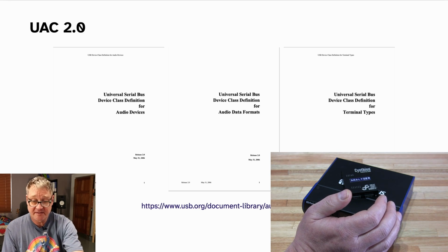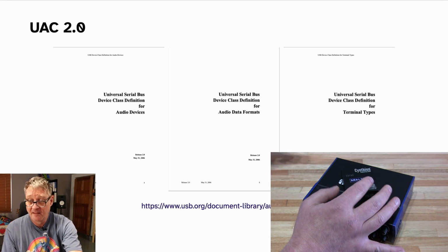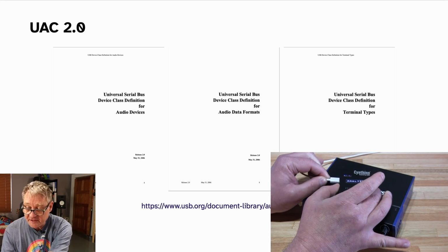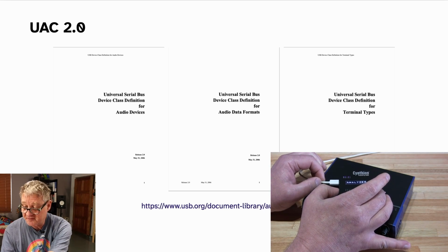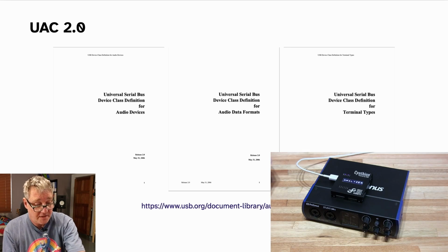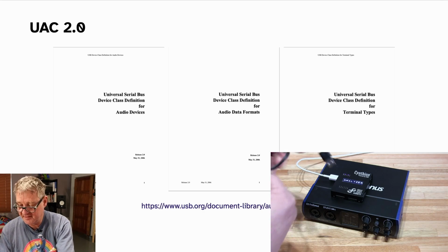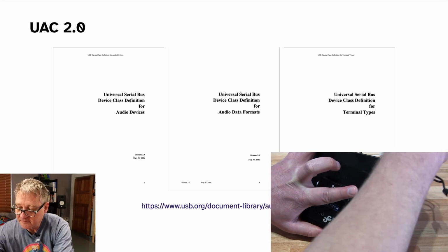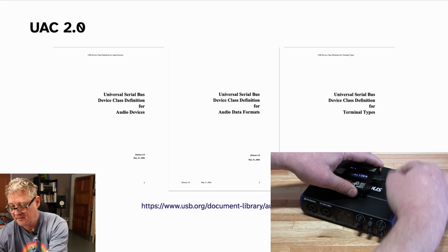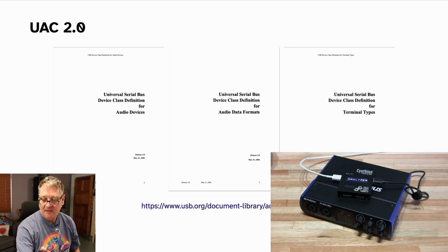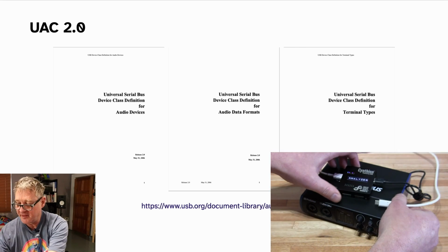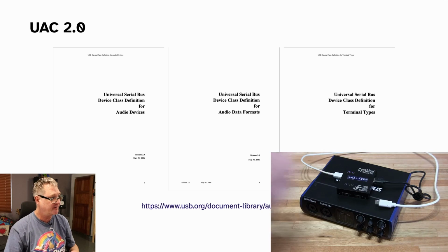So to connect it, we start by plugging the machine running the Packetry software, which we use to actually look at the captured traffic, into the control port. Then we can plug the interface itself into the target A port, and finally the host into the target C port, but we can hold off on doing that because we want to capture the enumeration of the device.